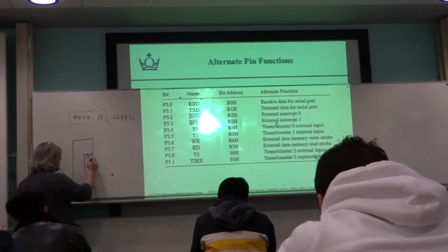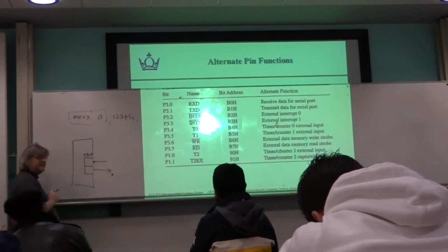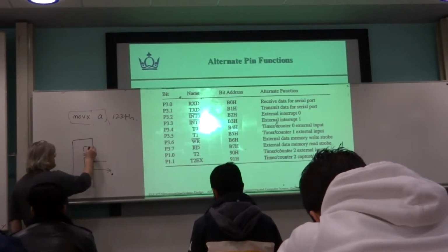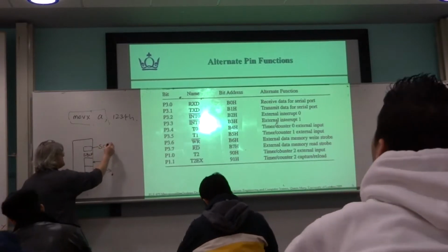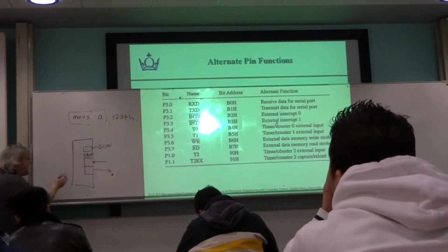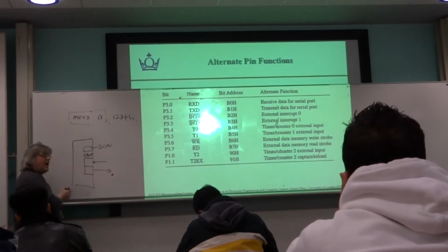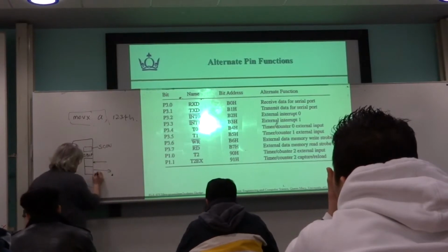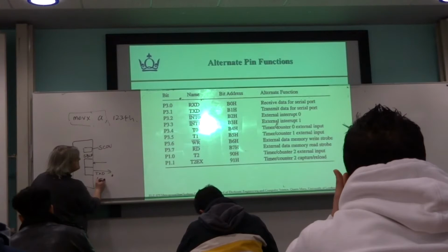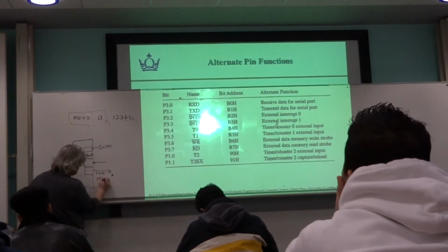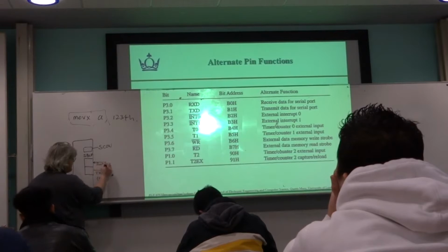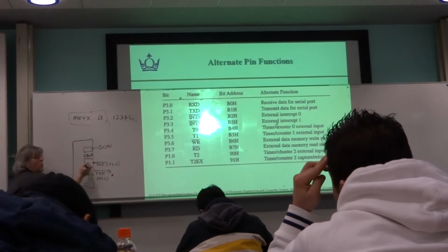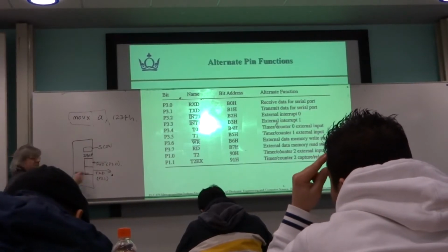There's a pair of them which are actually known together collectively as SBUF. Just pay attention. Stands for serial interface buffer. And there's another register called SCON, which stands for serial control. SBUF, the input and the output, are hardwired to those pins. So this one is connected, this is the TxD pin, which is port 3.1. And this is the RxD pin, which is port 3.0. You cannot change that. Intel have internally wired that pin to the buffer and this pin to the buffer.